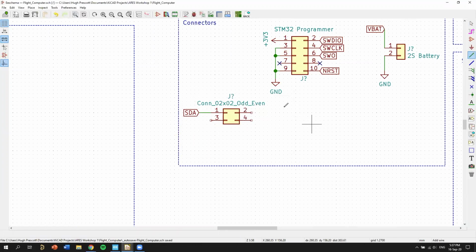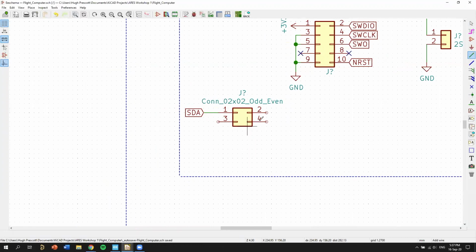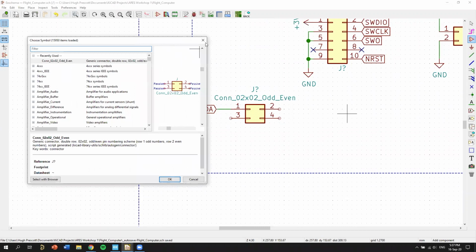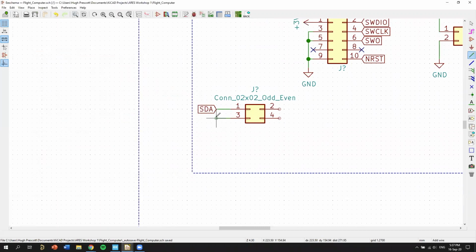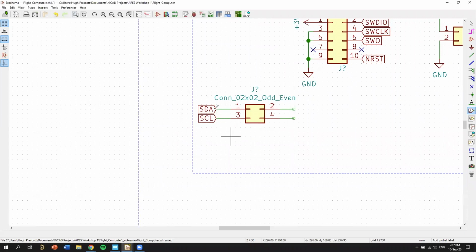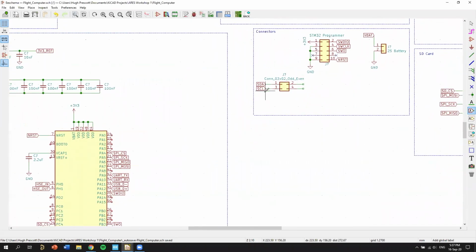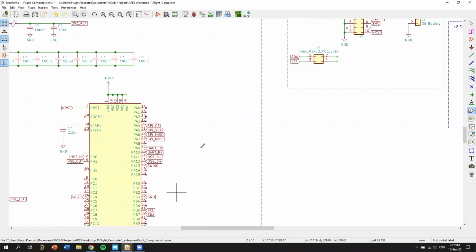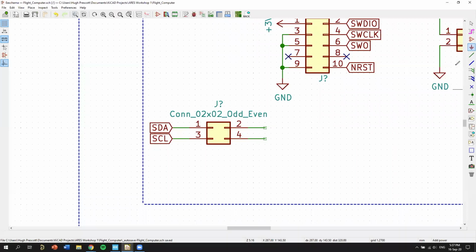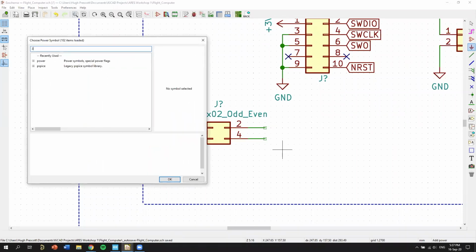We actually haven't done any schematics for a while, but if you press A, that brings up your part library, and then W lets you draw wires, and you can just double click to end them. So what next? And then these are global net labels, which just means wherever you see that, instead of drawing a wire between SCL here and then SCL down here, it just assumes that there's a connection between the two. And then I'm just going to put our ground and 3.3 volts.